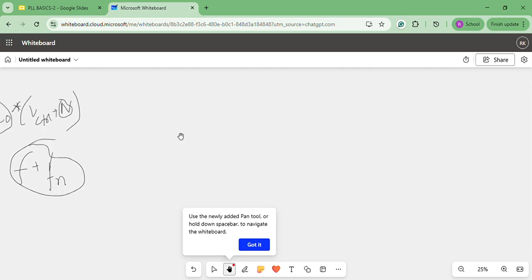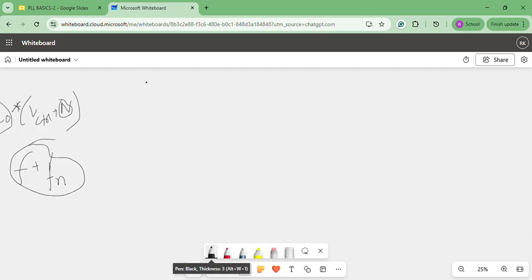So let's take an example. Suppose our supply voltage VDD, for which we are designing our VCO, is 1.8 volt. Before the VCO, as you already know, there is a charge pump, then a low pass filter, and finally the low pass filter will generate a control voltage.